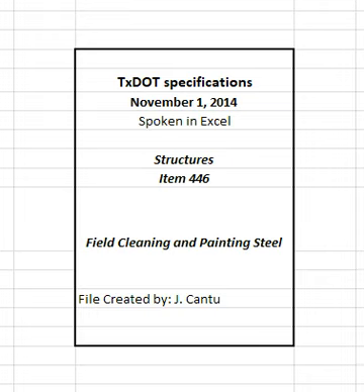When the final field coat does not have a uniform color and appearance throughout the structure, correct it by the use of whatever additional coats or other corrective measures are required. Remove freshly applied paint that has not yet set with the use of suitable solvents. Remove dried paint films with blast cleaning, scraping, or flame torches, as approved.